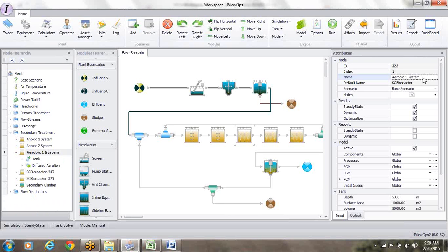Now you may ask, well, why did you split this aeration zone from 1 to 3? Well, what happens is most plants we are finding the liquid does not mix longitudinally all the way between the front and the back. There is division if you run a more sophisticated analysis and do tracer studies. There is demarcation between the front end and the back end, and also they are using different DO set points in different parts.